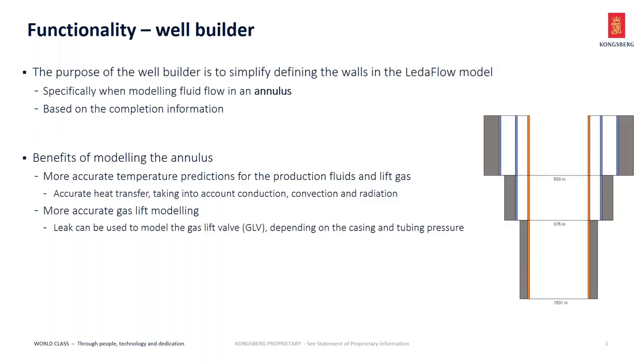Okay, so the first functionality I would like to introduce is the well builder. So the purpose of it is to simplify defining the walls in the LedaFlow model, and specifically when modeling fluid flow in an annulus. So this is a little bit complicated to do by defining the walls manually. So that's why we created this well builder, to make it easier to do that based on the completion information. So I'll just demonstrate that afterwards. So it's possible to model different annular spaces in LedaFlow, both the A annulus and the B annulus, depending on what you want to do.